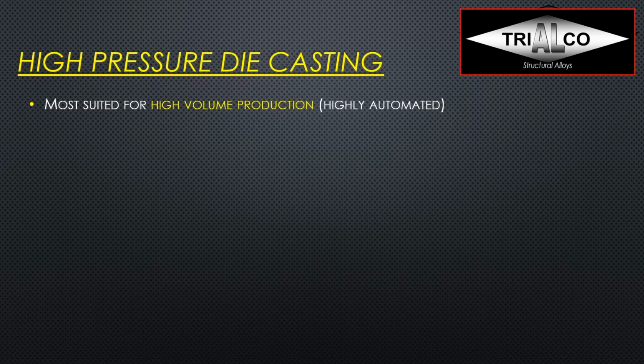The dies are very expensive, and so you would not make high-pressure die castings for a production volume of just 10, 20, or 100. Usually, high-pressure die casting is used when you have thousands, if not tens or rather hundreds of thousands of parts to be made. Another beauty of high-pressure die casting is that it's very dimensionally accurate, so you get very tight tolerances, which can often help you save on machining later on.